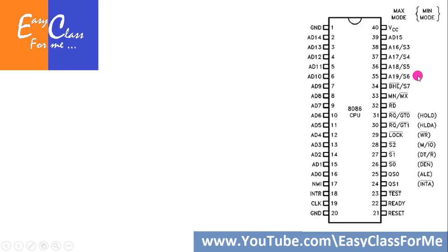Now, after having multiplexed these address buses, at a particular time the address is given and at some other time the data is given. Addresses are not given very frequently: once you have specified the beginning of the data segment from where you want to access data, or the code segment from where you want to access your code, the next operations will be reading and writing into those memories or accessing data. So the address is given once, and then there are multiple operations to be performed. The bus will be used as data bus at that time.